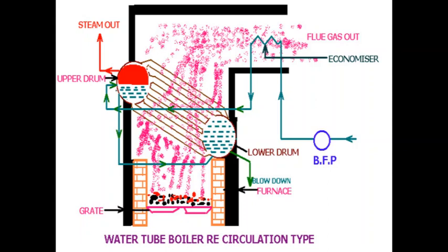This is a natural type of arrangement which was made based on the principle of thermosyphonic action, where the water column in the tubing outside the furnace and the water-steam mixture in the bank tubes, the density difference creates the circulation force within the water-steam circuit.